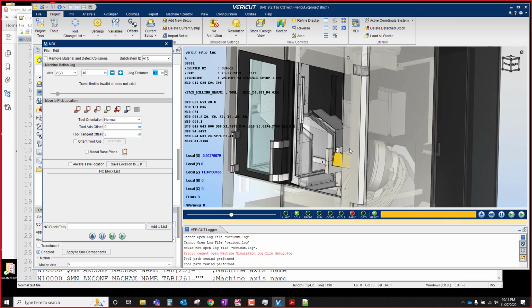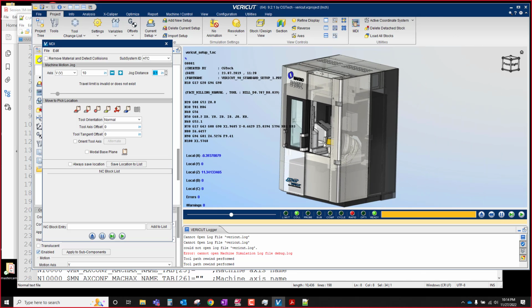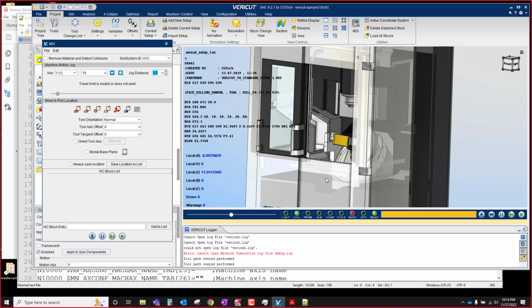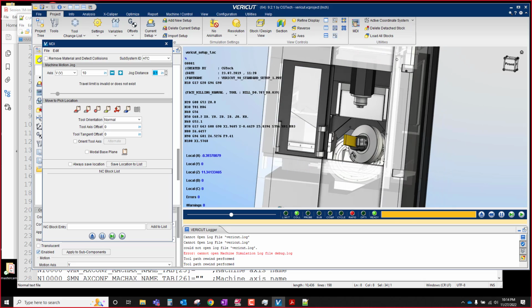But somebody has to build that logic into it. I mean, I've done basically a 6-axis hole popper EDM that had a 2-axis rotary table. It had both Z for moving the spindle up and down with these little tiny EDM tubes, and a W axis, which was a support that slid up and down, and all kinds of crazy stuff.